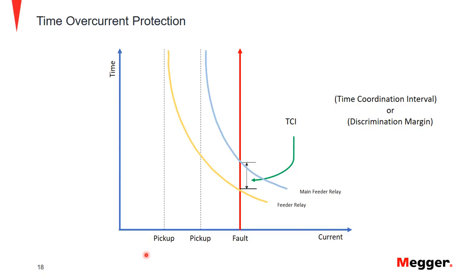There's factors that can influence this time here. And what they can be is the breaker fault interrupting time, because one breaker operates different in summer than it does in winter. It could be one model of breaker on one end of the feeder versus a different model breaker. So there's a little bit of flexibility in everything. So when you look at the system as a whole, you have a lot of small errors that need to be added up so you can actually get this TCI or this correction factor here. You can actually get this guy pretty close, but you're never going to get it exact.